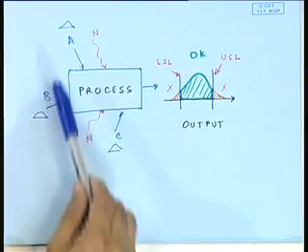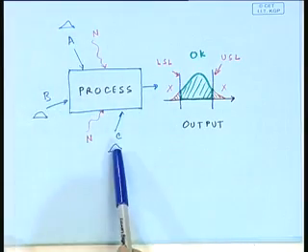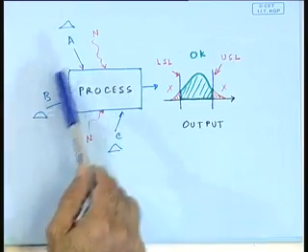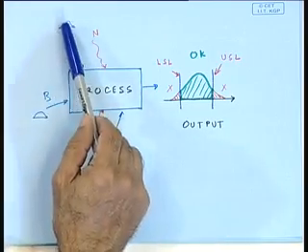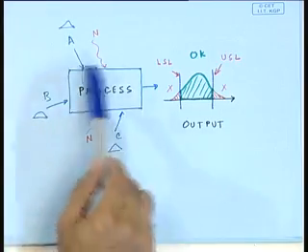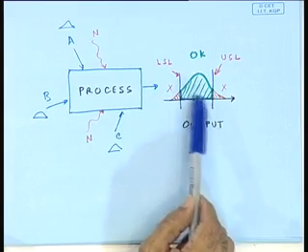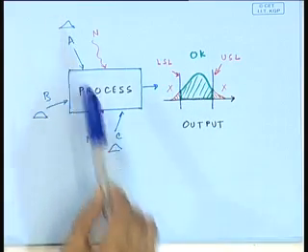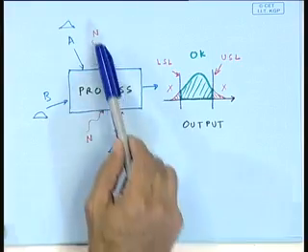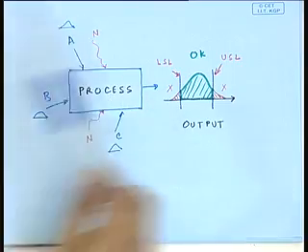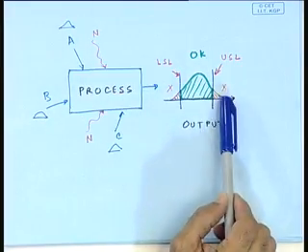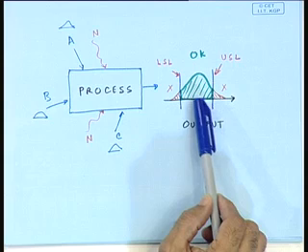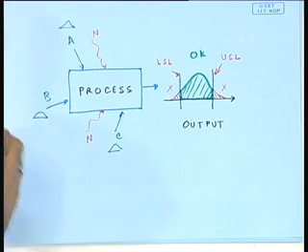That means we have to go back, and if you look at the process diagram, there are these factors A, B and C. Perhaps they have been set in such a way, or perhaps the controls on them are not good enough to keep this process well within the specification limit. When you look at the output of the process, perhaps there is too much variation in these, and perhaps there is too much noise also. These are the reasons why my output may be beyond the specification limits and my process capability may be poor.